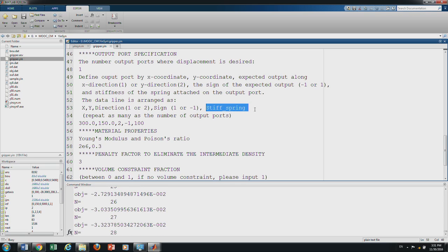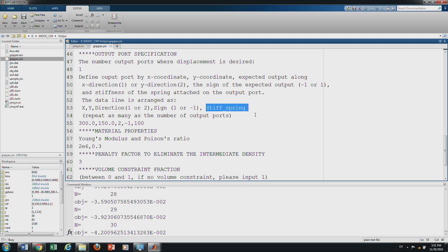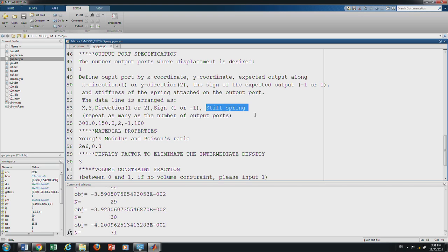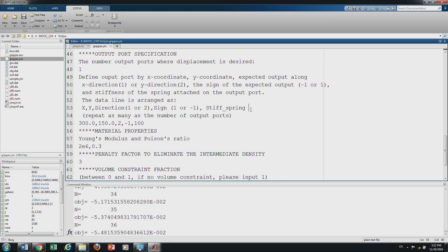Additionally, we also need to have an output load or an output spring, because a compliant mechanism output will always act against some loading or a spring load like an elastic object, but there could be problems where there is neither an output spring nor an output load. How do you do that? Like in rigid body linkages we can also pose this. To avoid this need for the spring constant, there have been attempts to get different formulations which we will discuss in one of the lectures, but you note that that is an important thing.